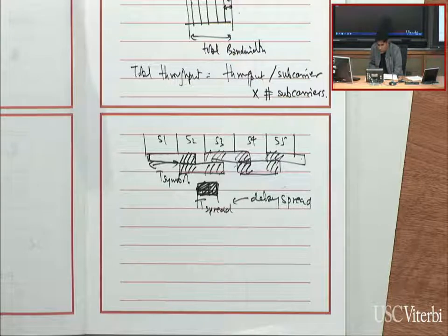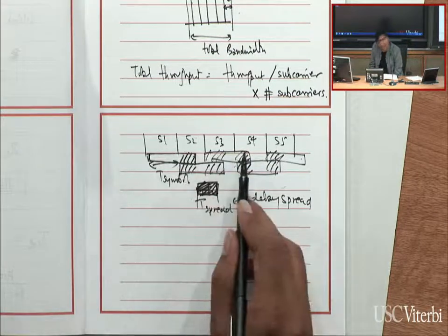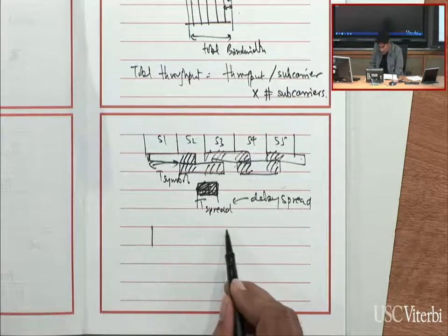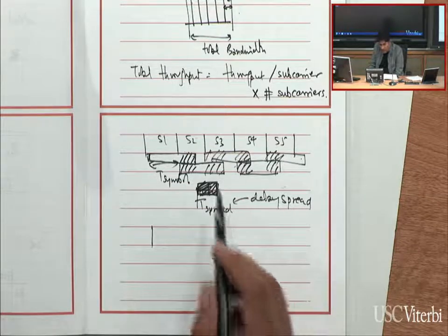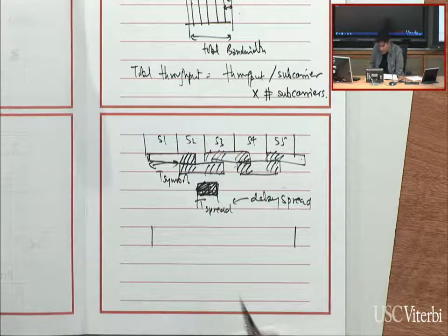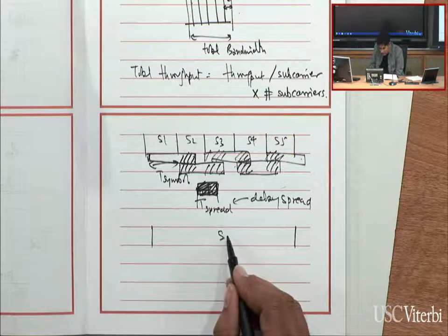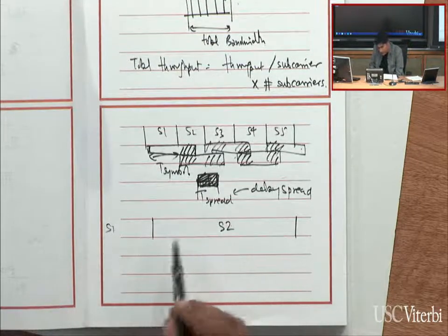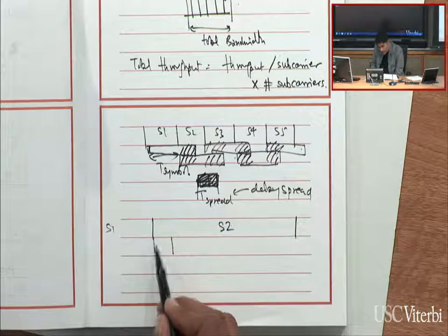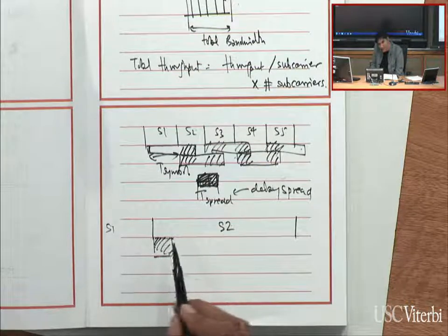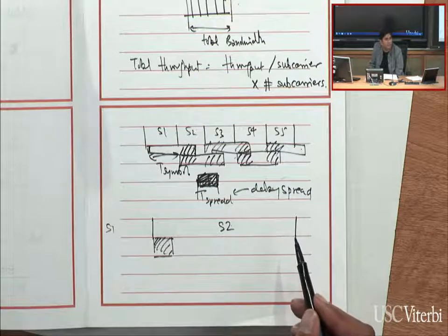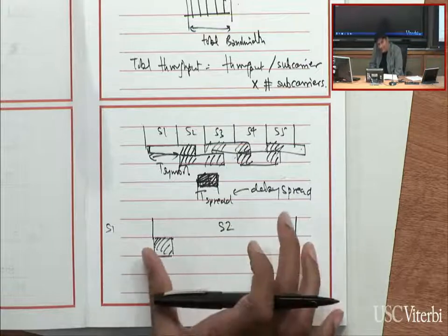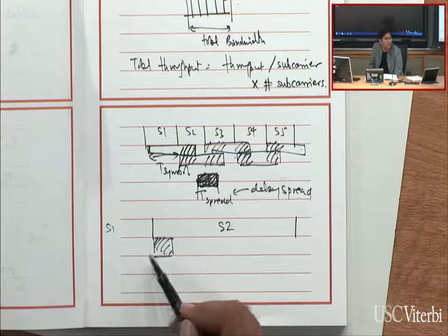So the idea is that if I could stretch my symbols out to be larger, so make the symbol duration larger, cut down the rate of that stream. Maybe my first symbol is only 1/30th that, or let's take a simple example like this, let's say it's only 1/5 of that. Let's assume this is my second symbol that's coming. Here's my first symbol before that. Now for the same amount of spread, the previous symbol will only interfere with this small portion of the next symbol. So by extending the size of the symbol, I can reduce the interference from the previous symbol.